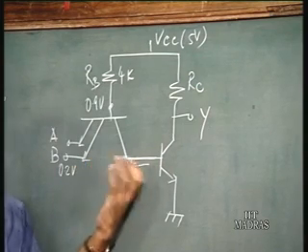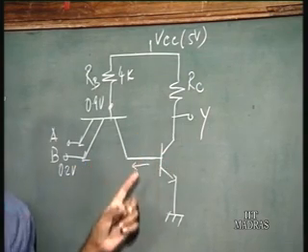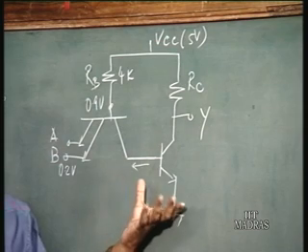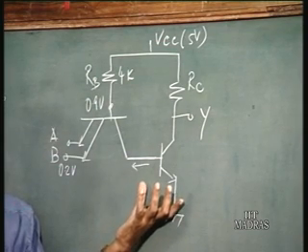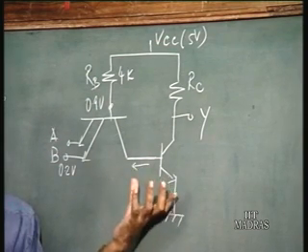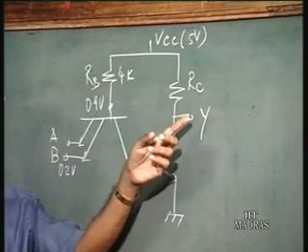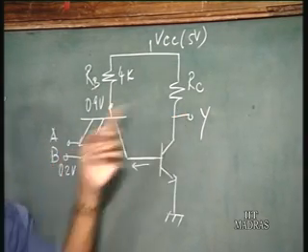But there is no current, so this transistor actually gets no base current. So what is the state of this transistor? It is off, it is cut off. So the output is going to be high. All right, when any input goes low, the output is high.